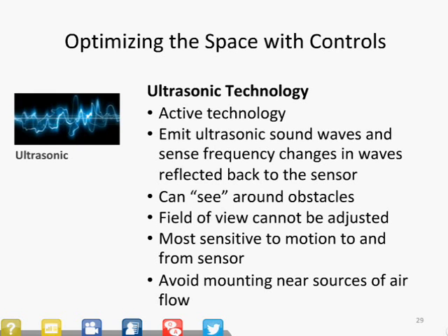Next is ultrasonic technology. Ultrasonic sensors emit high-frequency sound waves into the space. That's different. It's an active technology, unlike passive, where it's not emitting into the space. Ultrasonic emits a high-frequency sound into the space, which is then reflected back to the sensor. If the sensor detects a change in frequency in these waves, it triggers the lights to turn on or turn off.